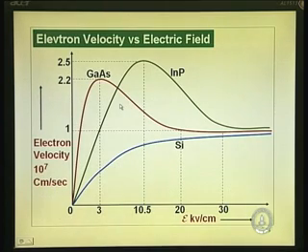Because of that, gallium arsenide, you can see it gets accelerated fast. See, the slope is higher here. Notice these 3 curves: silicon, gallium arsenide, indium phosphide. Mobility of electrons is much higher than that of silicon. So, v is equal to mu into E, steeper compared to silicon. Mobility of electrons in indium phosphide is smaller than that of gallium arsenide. So, slope is slightly smaller. Okay. v is mu into E here.